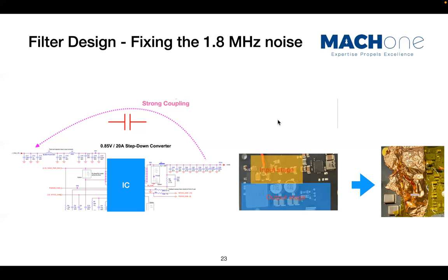So how can we prove this, right? The way I prove it, first I actually moved one of the inductors on the input stage further away. As you can see here, there are two twisted lines here. That is where I moved the inductor from this point further away, but that doesn't help because these two cables also couple noise. So the next stage, what I did is simply shield the whole output stage filter, right? Using a copper tape. But the copper tape needs to be bonded and have a very good electrical connection to the grounding point, which is here, okay?